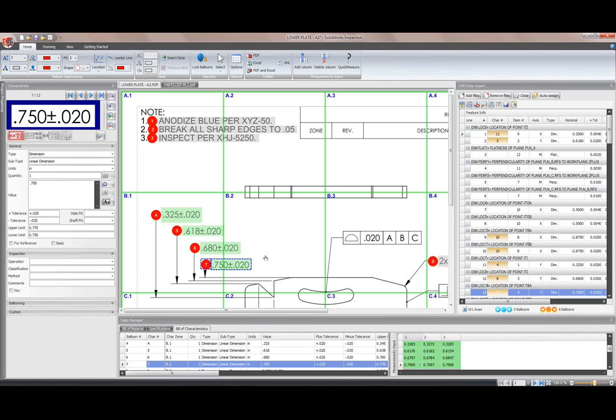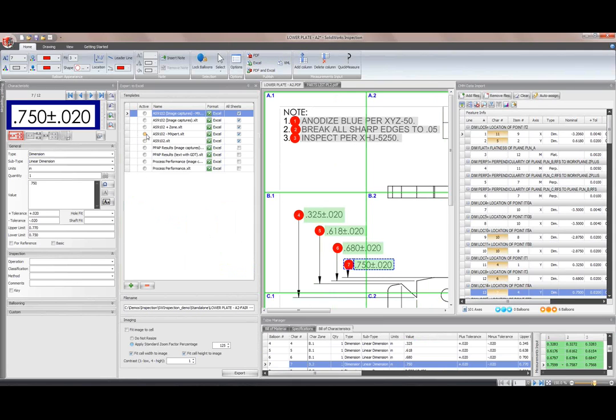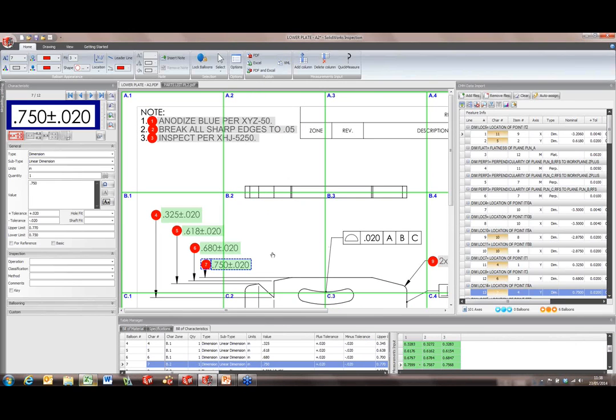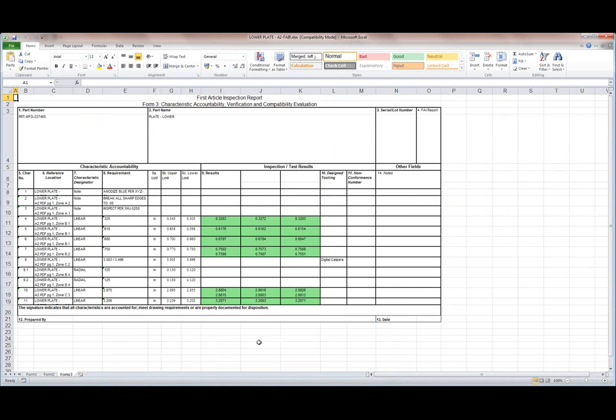If you're testing a batch of 50 parts, for example, with the CMM, we can get all that information in very quickly. You only have to assign the things once if it's not assigned up correctly, but you're going to do all 50 tests all in one hit. And we can export again an Excel of this with that same template, which will push this out into Excel and give us the range of values that have been measured and whether they conform to the correct tolerances or not.